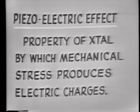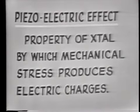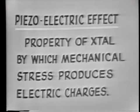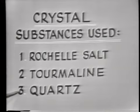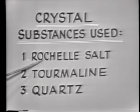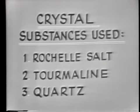Now, let's recap a few of the points that we've discussed in this lesson. First, we saw the use of the crystals. We said that the crystal must exhibit the piezoelectric effect. And we define the piezoelectric effect as the property of a crystal by which mechanical stress produces electric charges, and conversely by which electric charges produce mechanical stresses. Then we saw the 3 substances used: Rochelle salts, tourmaline, and quartz. We said that Rochelle salts exhibits the piezoelectric effect to the greatest degree, but that quartz is most generally used because of its mechanical strength.